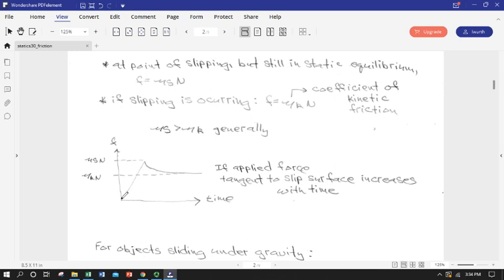And generally speaking, the relationship between mu sub s and mu sub k can be defined in terms of how that friction force is going to respond as we increase the shear forces applied to a body to make it move. So if we're measuring this in a lab, say, and we're measuring frictional force in terms of resistance to visible measurable slip with increasing applied force, you'd see, if we were increasing our applied force linearly with time, say, your friction force would kind of go up linearly.